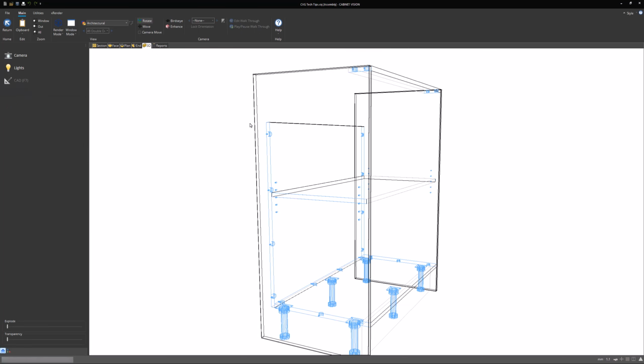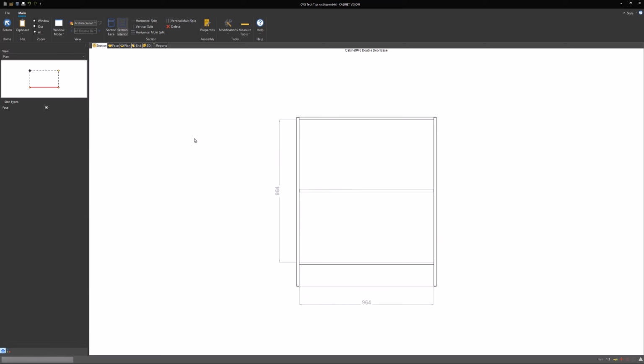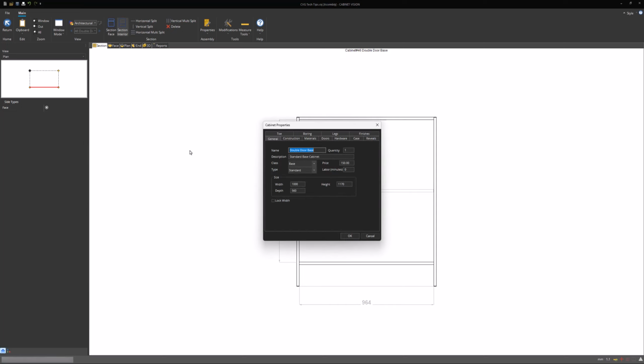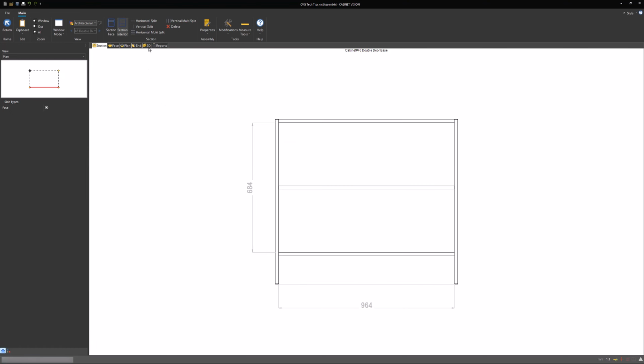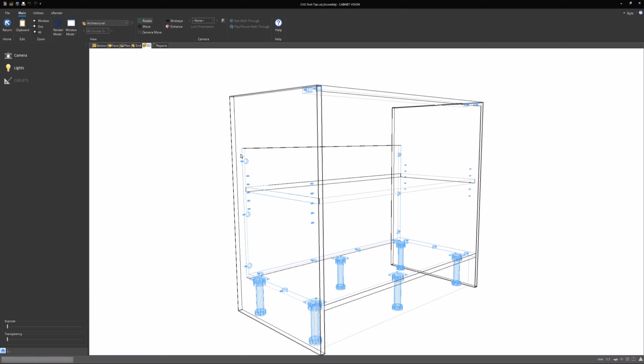And then if we take a look here, you'll see that my back has now dropped down 200, but the difference being that if I go to section view now and modify my assembly again, and I'll set this one back to 870, we should see that that has now remained parametric.